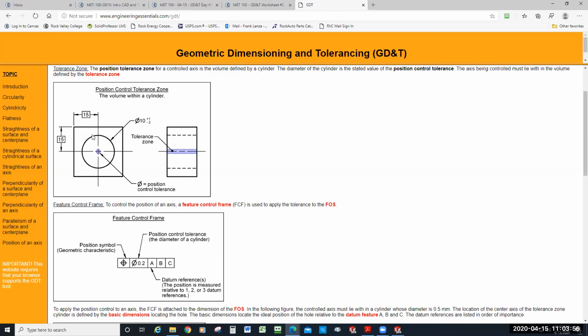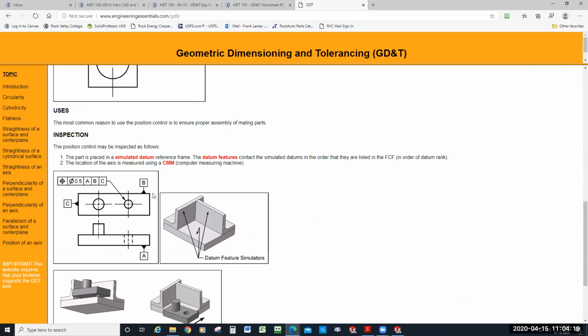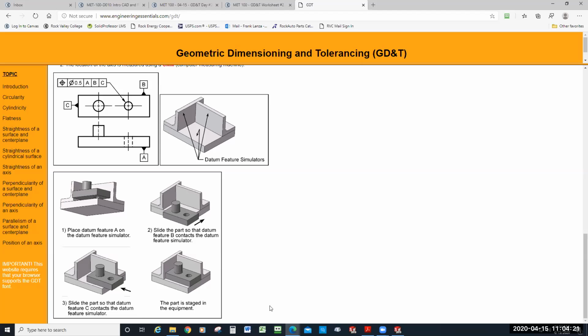So if I were to datum here and here and not worry about datuming on the back side of it, or the front side of it, whichever one happens to be my 3rd datum, I could check this hole, and even in a fixture like this, if I stick a pin in here, and let's say I only stick it in so far, and I take a measurement back to this surface, and it all looks good from here to here.